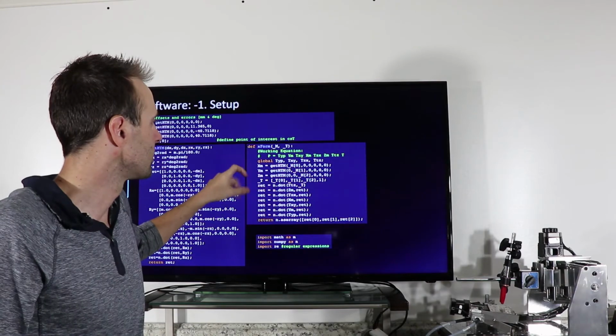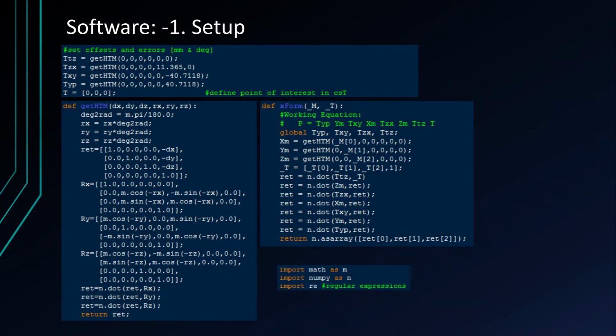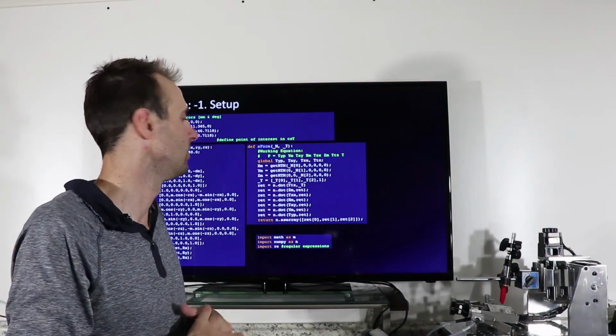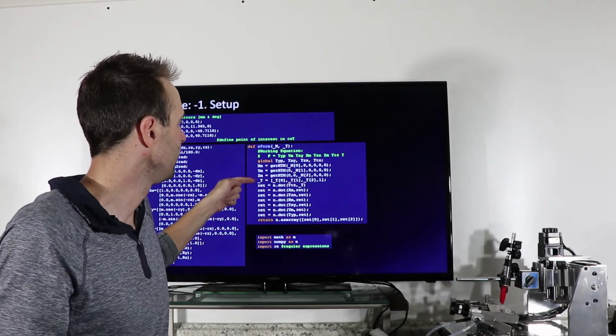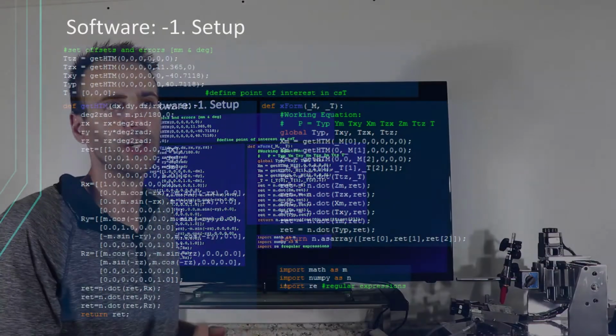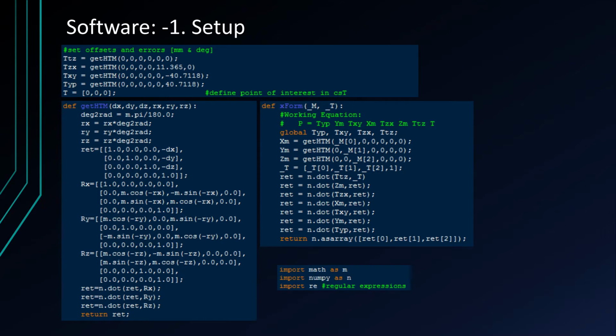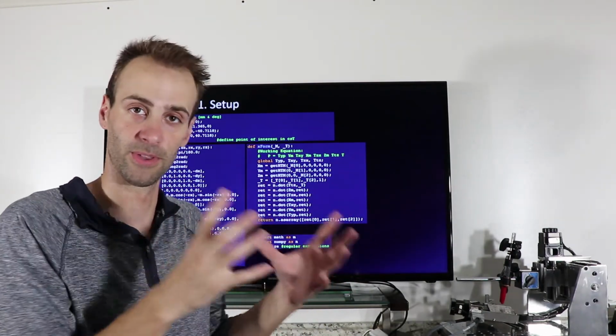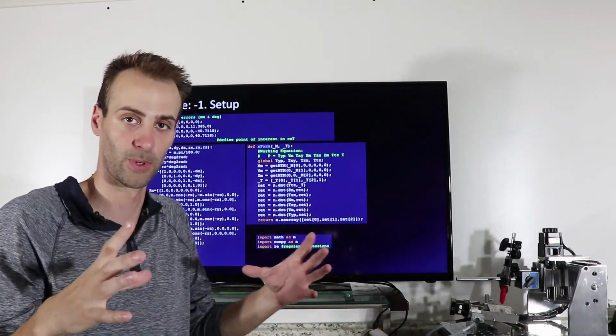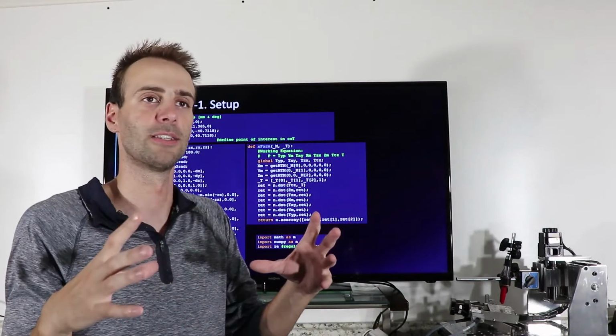The way this works is, my XM, YM, ZM, I essentially add those in one by one in return matrices. Then I build a tool matrix, basically reshaping that array, because right now it's a list of 3, and I turn it into a matrix with 1 by 4 dimension, because remember our HTMs for a 3-axis system, or even a 6-axis system, are 4 by 4.